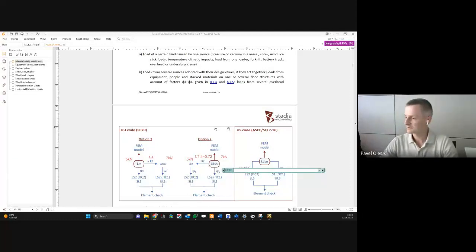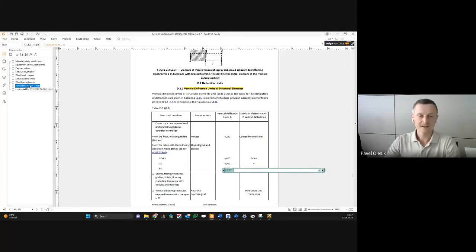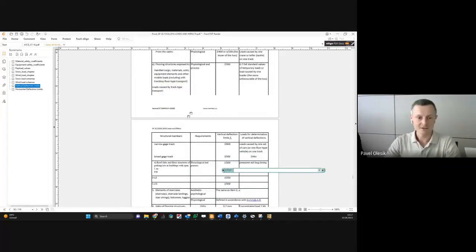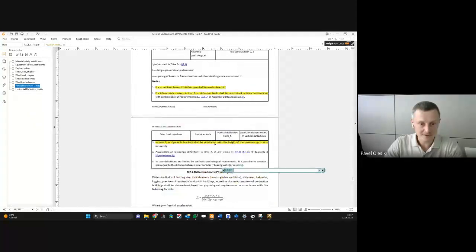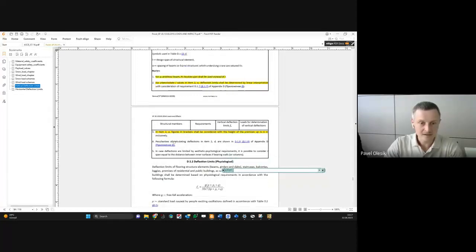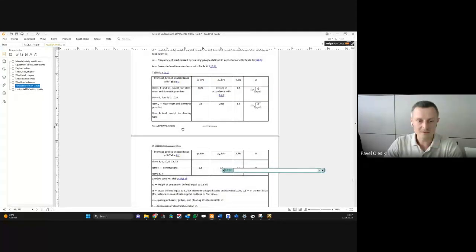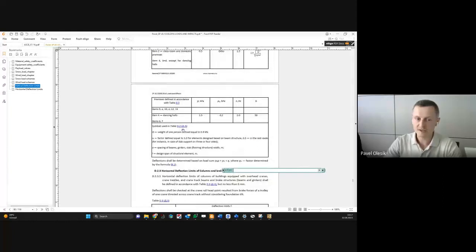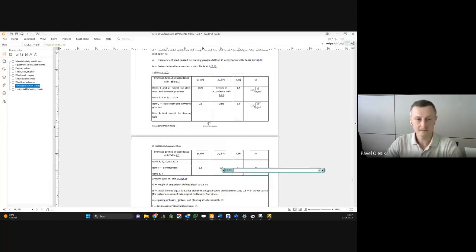What's your question? We talk about this duration factor. Duration factor for SLS? You mean that we can decrease this for SLS, for 50% snow? Yes, sometimes we use this duration factor just in SLS for the combination. You mentioned an important point: in our code it's written that for SLS combination we can decrease our snow load by 50%.